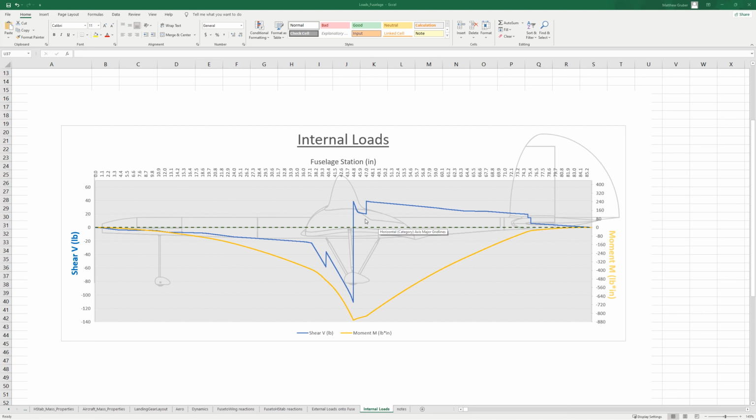Actual aircraft programs these days have hundreds of these maneuvers considered that are each potentially critical. For instance, you'd have maybe a side slip at such and such speed and altitude, and another side slip at another speed and altitude, and those might be critical for various areas, like where the V-fin attaches to the fuselage. And each of those maneuvers will be balanced. So for the fuselage, we might have a 2-point landing and a 3-point landing, and in a 3-point landing the nose gear would be involved, so you might have more of a moment right behind the nose gear.